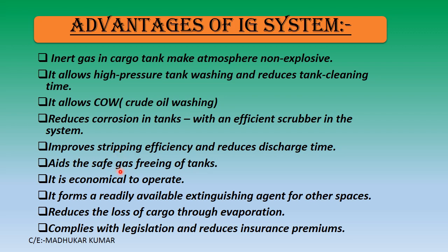It is economical to operate. It forms a readily available extinguishing agent for the spaces. It reduces the loss of cargo through evaporation, complies with the legislation and reduces the insurance premium. These are the factors which give the advantages when the IG system is installed on board ship.